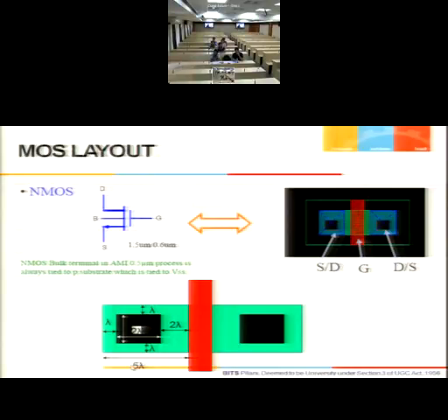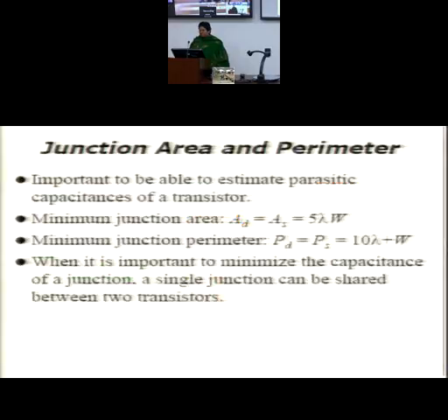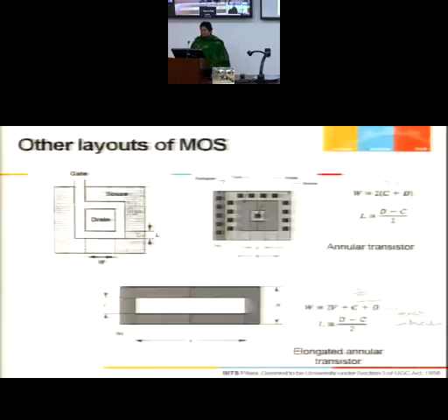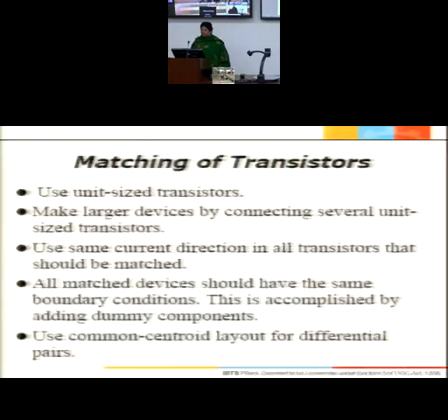Okay. So we have a minimum junction length of 5 lambda. And the minimum junction width should be, again, 2 lambda plus lambda plus lambda, that is 4 lambda. So you cannot have junction dimensions other than this, as per this figure that I have taken, based on the design rules. Now suppose you have to create a big transistor. Let me show you a big transistor.